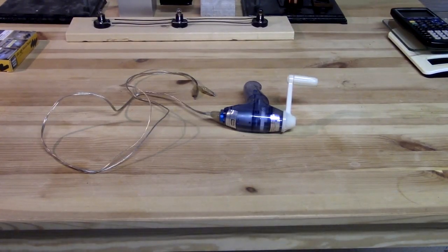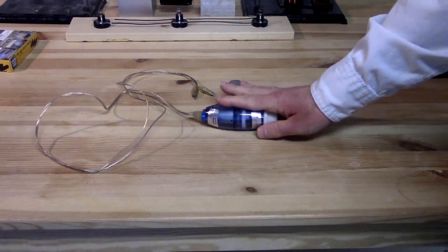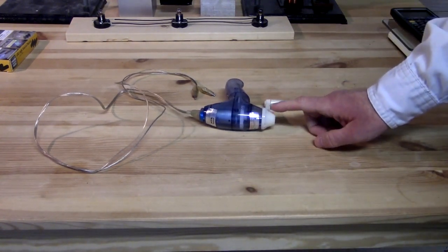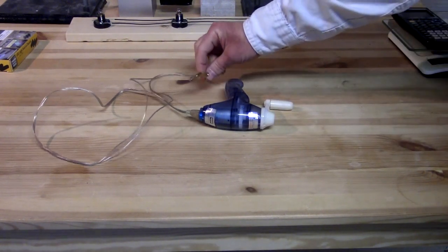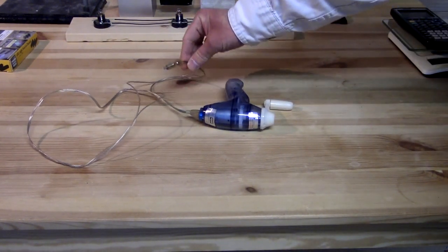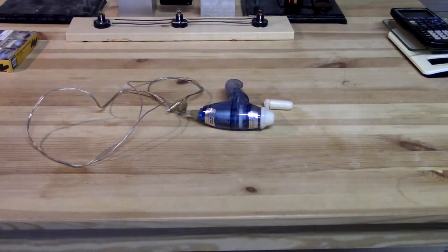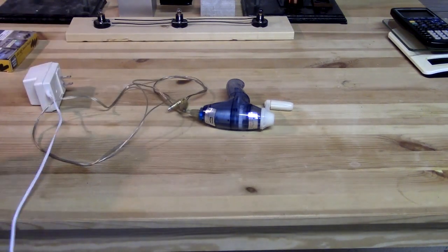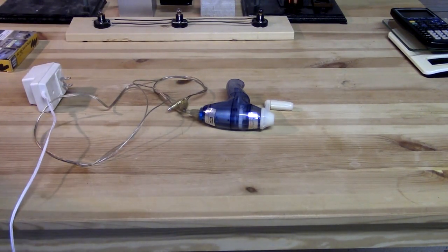Okay, one more thing I'd like to show you quickly here. The Genicon is being used as a generator in all of these demonstrations, but I told you a few minutes ago in the lesson that there's really not any difference in terms of how these things are built between how a generator is built and how a motor is built. Right now what we've been doing is supplying mechanical energy as an input by cranking the handle, and the output has been electrical energy. But if that's how it works as a generator, I ought to be able to reverse the process and take a power supply and connect the power supply to the Genicon.